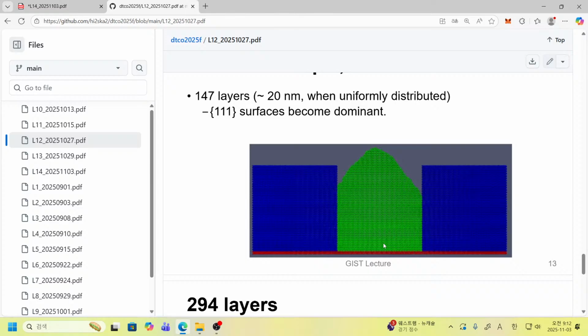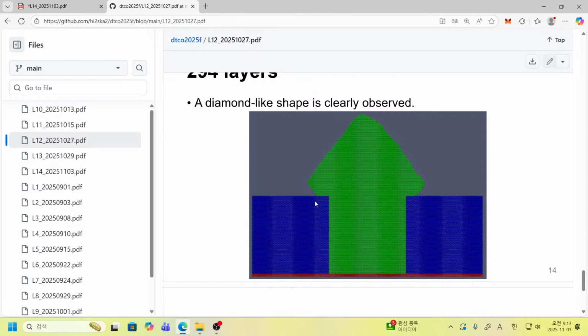In this example, our structure starts from just a trench shown here. Here we have a trench, and what is it? Initially we had a certain fin here. However, the entire fin was etched away, even the internal fin covered by STI is etched away. After that, we start our selective epitaxial growth starting from this point. That corresponds to a case where we start from the bottom of STI, or even under the STI top level.